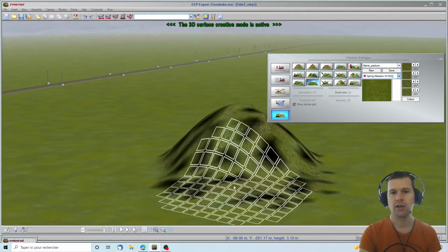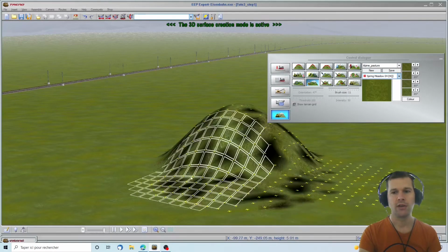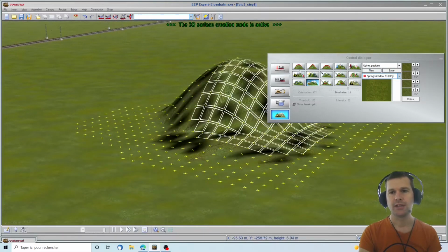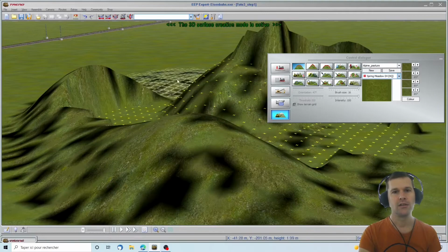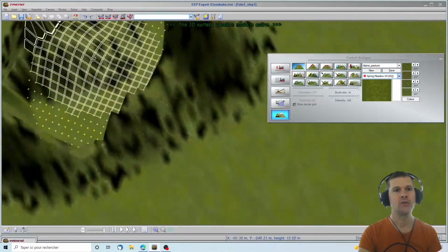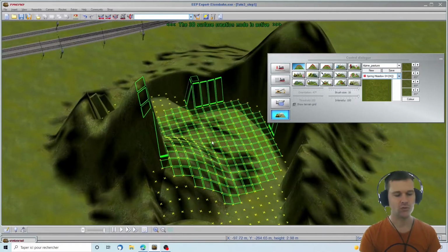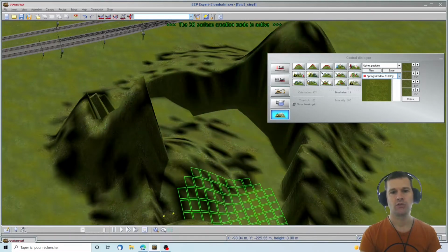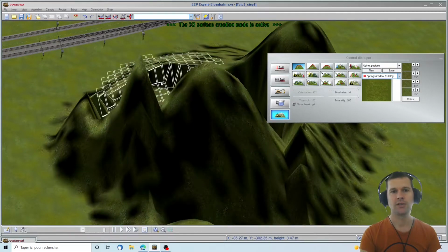Then you have also the possibility to lock some terrain. When you use this function and click, you have yellow crosses. And that protects this area from being modified, as you can see. Doing on it, still building, and here, let's have a look. Where the crosses were, nothing changed. To remove them, you only have to press Control. And then you can remove the crosses, and landscaping can be done again on these surfaces.